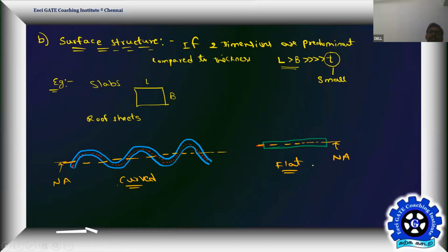This is asked in some of the interviews and also in some examinations. Which roof sheet do you prefer? Is it a flat sheet or a curved roof? Curved sheet. You might have seen at your home or nearby homes that somebody has used this kind of sheets for construction. Sheet means a steel sheet, thin elements basically. To call any element a sheet, its thickness should be less than 5 mm. Otherwise, we don't call it a sheet; we call it a plate.